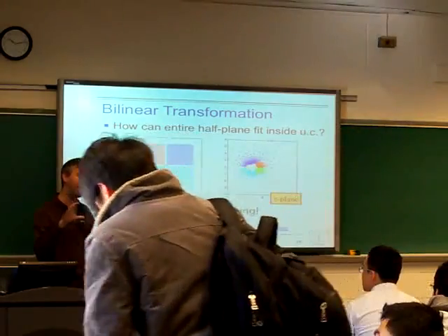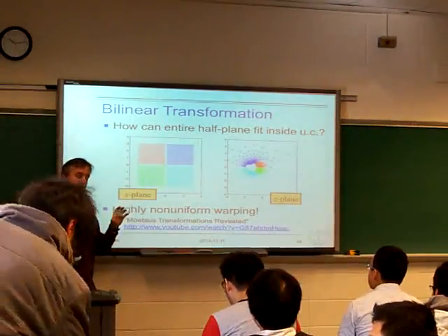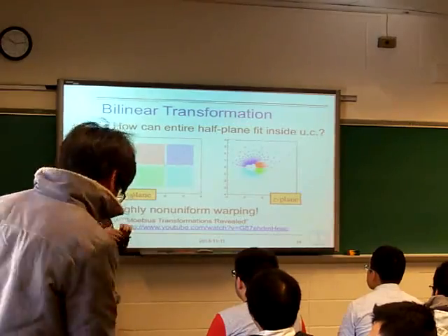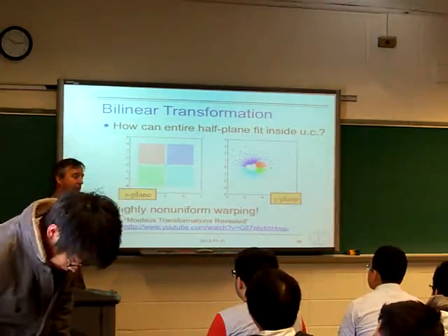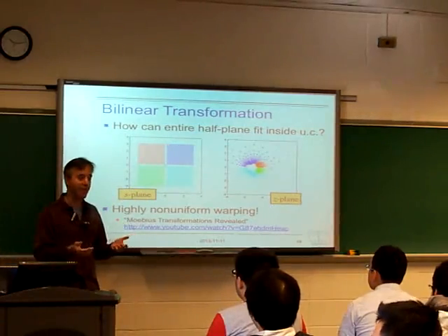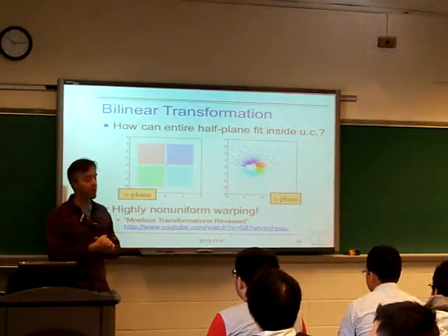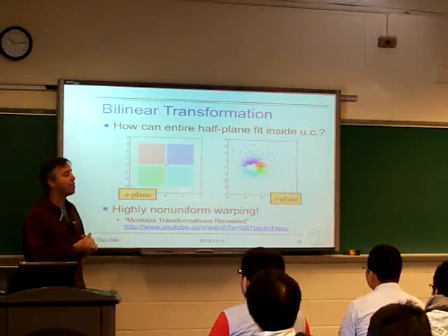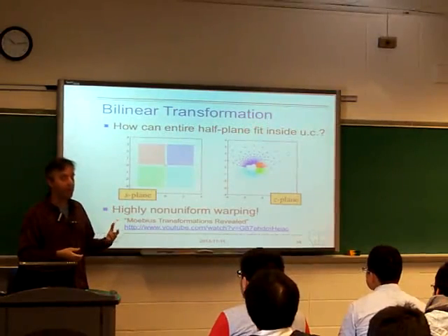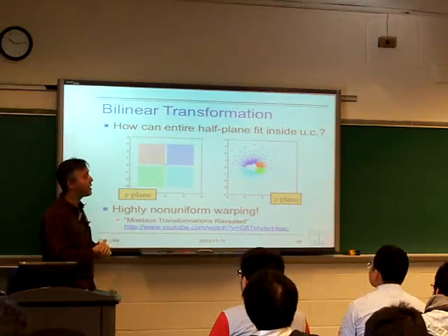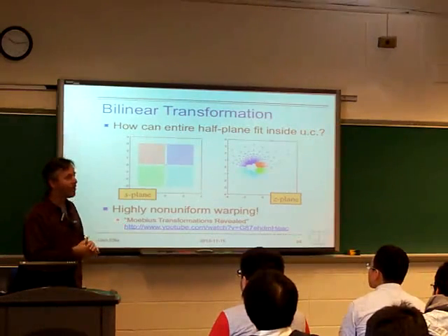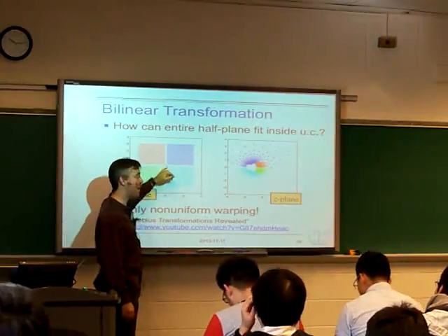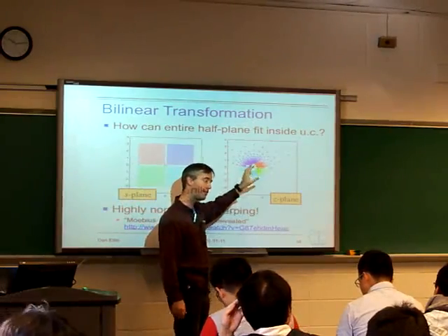We say, okay, we've got a limit on how close we're going to get to our response. We'll design a filter that'll just touch that limit, and it'll do it multiple times. And so once we have that constraint, these are the polynomials that give these equal-sized ripple responses. So they're the ideal solution to these things. And when we try and actually build these discrete time filters, we want to use those same polynomials, but they can't be exactly the same, because instead of trying to get the frequency response on the imaginary axis, we're now trying to get it on the unit circle.